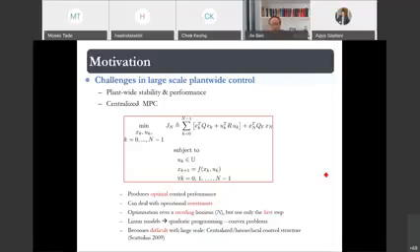One of the good things of model predictive control is that it can deal with operational constraints. This is particularly important in modern chemical processes where we often operate near the constraints. The MPC problem optimizes for n steps in the future, but only implements the first step. So in the next sampling time point, it does the optimization all over again with the new state information of where we are.